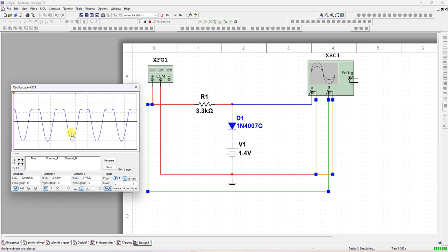See here, if I click AC, the area under this and the area under this will be equally divided. So that's why the waveform shifts. But if I click DC, observe the waveform. Now what is one division? One box is equal to how much? 2. So to check the output, from 0 to here is one box. 1 into 2 is 2 volts. Output is limited to 2 volts. So it has clipped all the input waveform above 2 volts. So it is positive peak clipper.